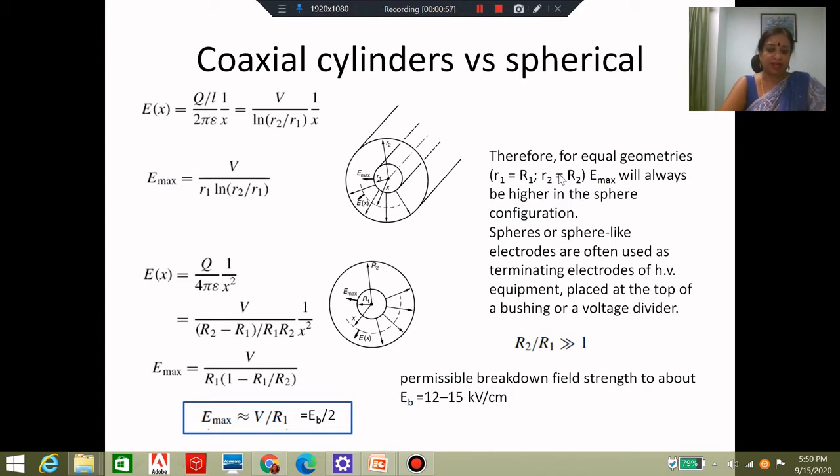gas insulated line. Now, we have generally been talking about air insulated transmission systems or air insulated transmission lines, where the transmission lines are out in the open and the air that is around it provides the insulation. So all we have to do to design the insulation is provide enough clearance. But air obviously has its advantages, but you may need quite a bit of clearance to provide adequate insulation in case the transmission voltage is very high.